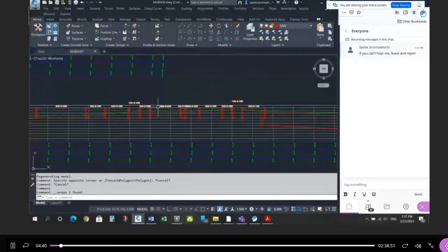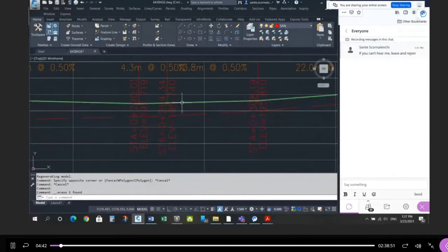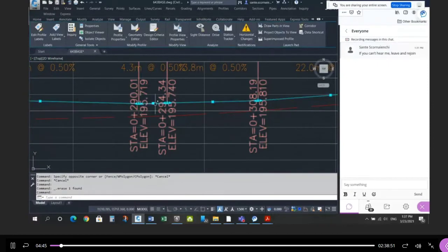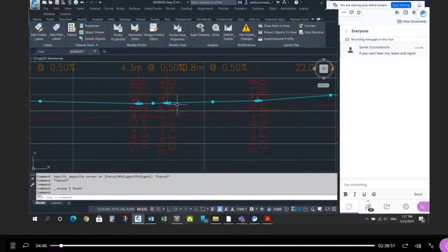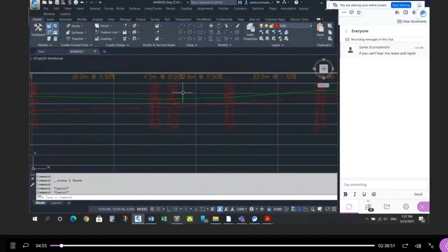Remember, we have the high point here and a high point here, and somewhere in the middle, we have the intersection elevation. Not the low point, but the intersection elevation. So there's the 195.740, which is the intersection of Street A, intersection of Street B, or the first intersection with Street A and B. Okay, so that was 4 marks just to have, sorry, 3 marks, right?